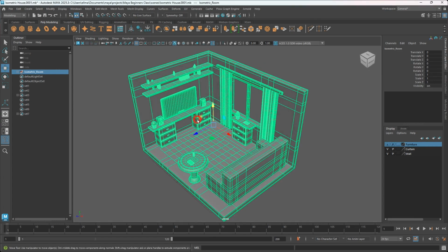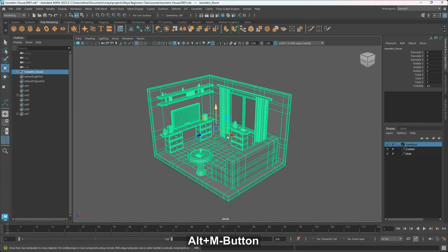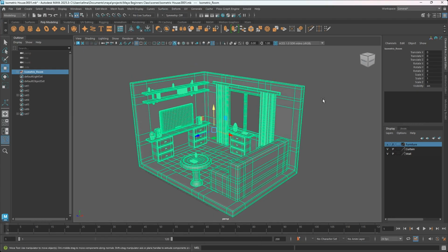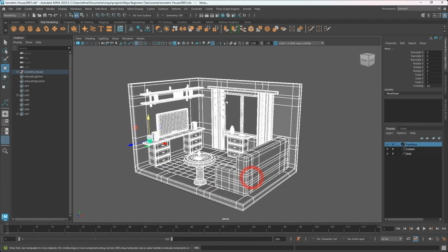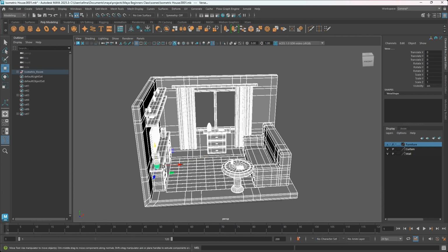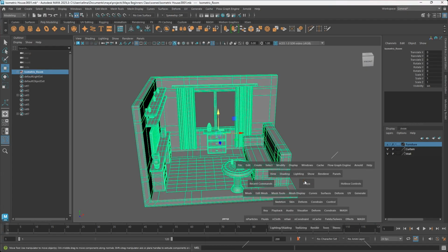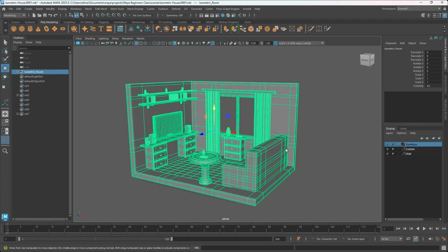All right. So this is what we are going to do before we start UV mapping. Most times things might get weird. So all you have to do is just to select everything from here. And when you do that, you can just repeat the same process. Freeze transformation, delete the history, and center the pivot. Of course, the pivot is not going to the center because of where it is here. So when you just select this, it is going to be centered. So this is how you can easily organize your models in Maya or organize your outliner.